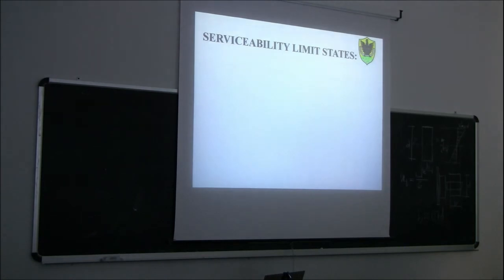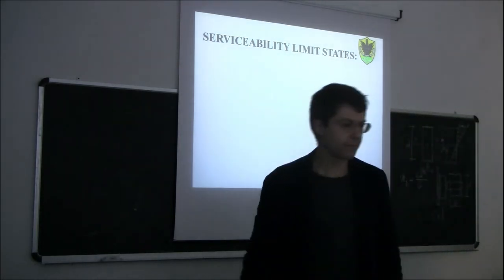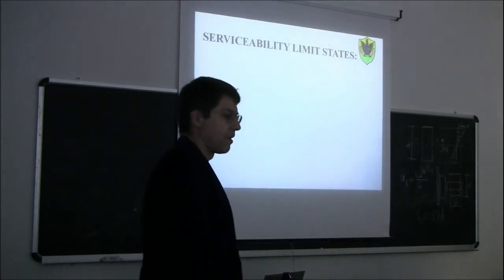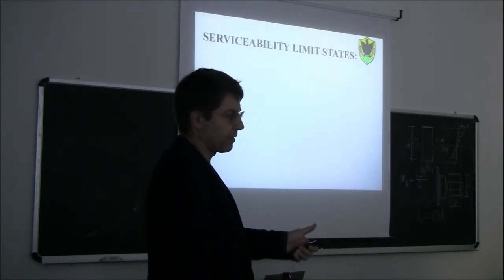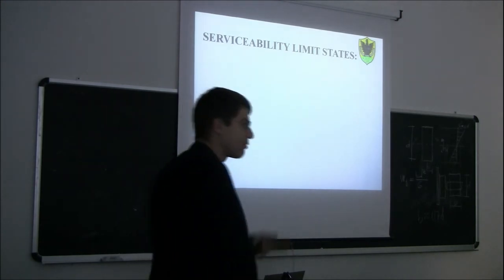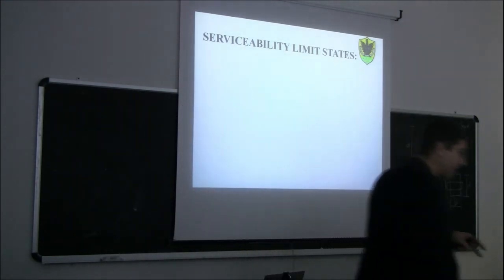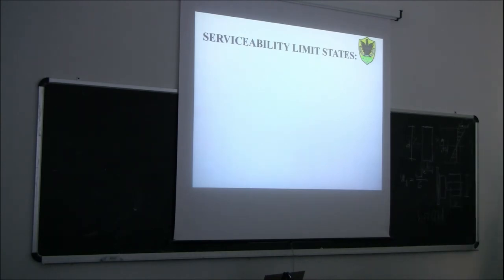Good. So what do we need to do now? What other verification do we need to do in our beam? So we designed for bending. What do you think? What other verification do we have to do to complete our design? So we need to do the serviceability limit states, which means 2 checks for deflections, instantaneous deflections and final or long-term deflections. What else? This is a serviceability limit state. What are we still missing to complete the design?